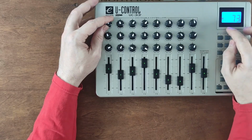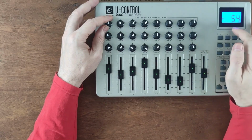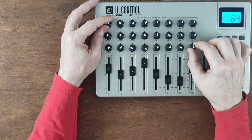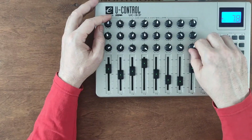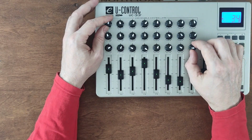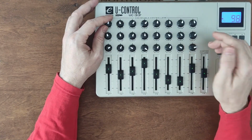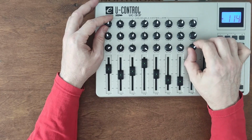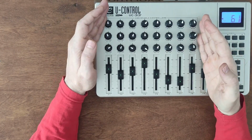If you find, for example, while moving one control, some different number appears in the left bottom corner, it means that this control, for example number 17, sporadically generates the control number while you are moving only one control. It means you need to clean or move thoroughly that control, for example a variable potentiometer, and clean the surface of the resistance and make that control more stable.